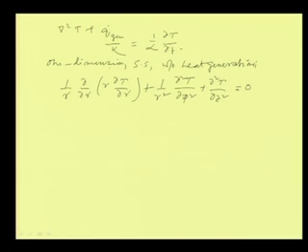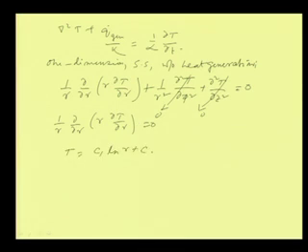And again, because it is one dimensional, these angular and axial parts go to 0. And then what we find is that 1 by r del by del r of r del T by del r is equal to 0. From this equation, you will find T as C1 ln r plus C2.